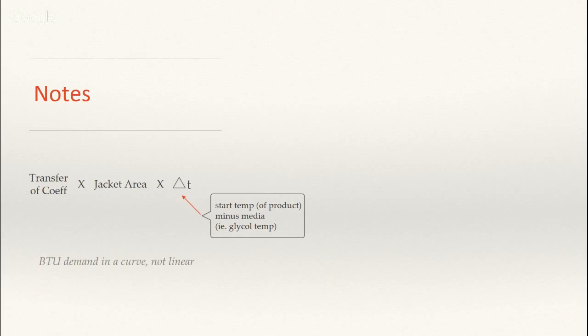When I do the calculations, I put a nice little package together of initial demand, full load demand, and average demand on BTU jackets to give to, for example, our boiler guy who's going to supply a boiler. Then he knows what that particular tank is going to demand. Or if you have 3 of them, then he knows, wow, I've got to supply 3 tanks with this many BTUs. You can do the same. That same information package can go to your cooling or glycol supply company, and they can help you determine the size of the chiller needed to cool the tanks down.